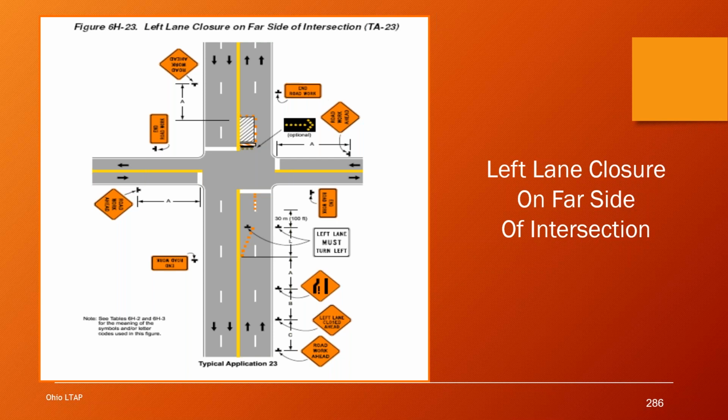You need to see if they have a heavy left turning movement volume or not. There's some discussion on how you could handle turning movements at the intersection, and sometimes they even say just eliminate turning movements in certain situations.